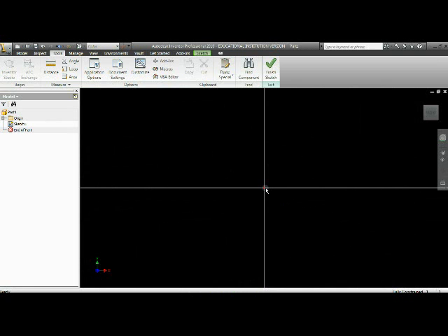I tend not to use that. I'm going to go back to Sketch and turn the grid lines and the minor grid lines back off. And also, if yours doesn't have it turned on, mine does, under Sketch, you would want to turn on Edit Dimension when created. So click that on and hit OK.